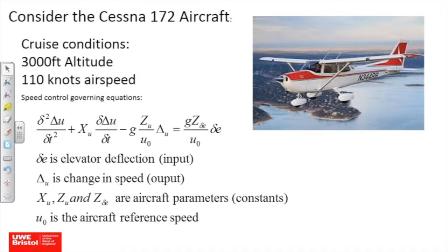Okay. It's not as bad as it looks. I'm not going to ask you to do that because half of you are asleep, but you're here, which is great. Okay. Have a look at it later when you've had the chance to recover from the project thing, because if you look in here, all you've got in here is, what order is that, I know it's a partial differentiation, what order of differential equation is that? Second order. If you get in there and rearrange that, what you find is that is a straightforward second order system. There's a second order relationship between what you do to the elevator deflection and the speed of the aircraft.